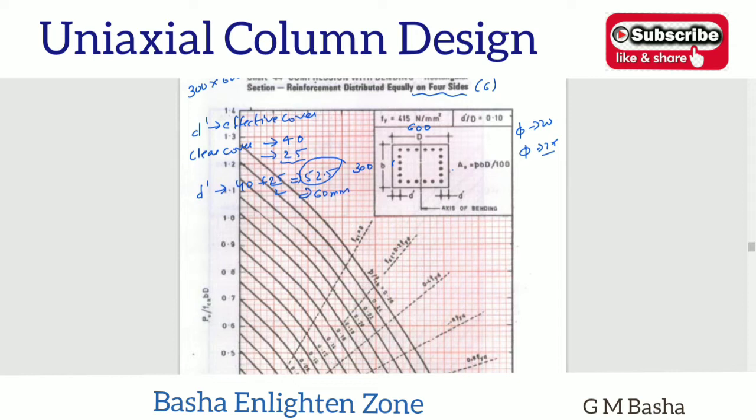If you want, you can choose 52.5, but in the end please check whether we are satisfying our condition or not. So I am choosing 60 mm, and I am going for the ratio d dash by d equal to 60 by 600, which is 0.10 on the chart. So this suits our condition. For example, if you take 52.5 divided by 600, you will get 0.08 only, which is almost the same value, no problem.